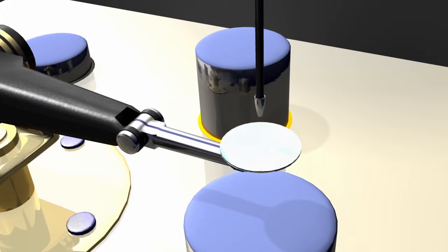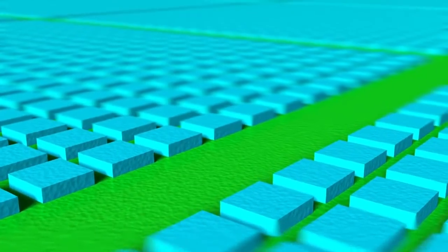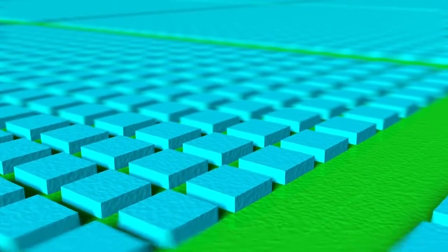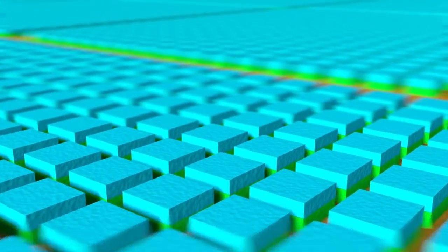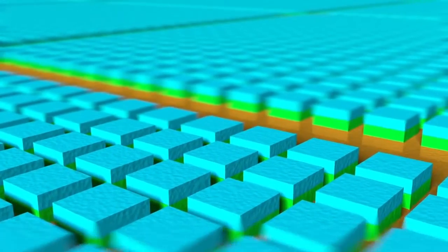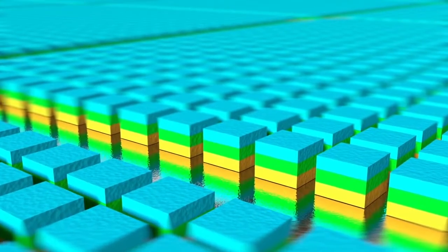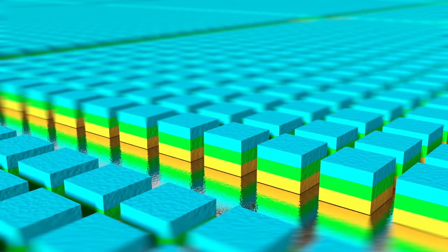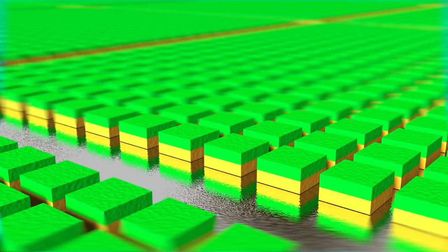Let's look at the surface a little bit closer now. The solvent uncovers part of the silicon nitride layer which lies beneath the photoresist. The application of corrosive liquids etches away the desired regions of the other layers in order to expose the silicon. Finally, the photoresist is cleaned off and the silicon regions are further chemically etched.